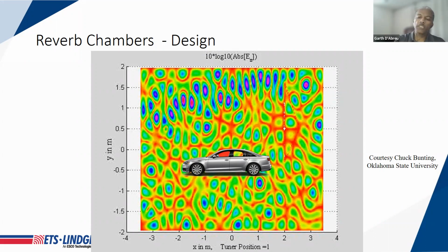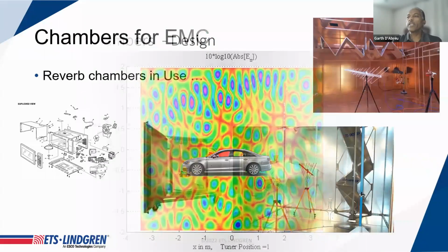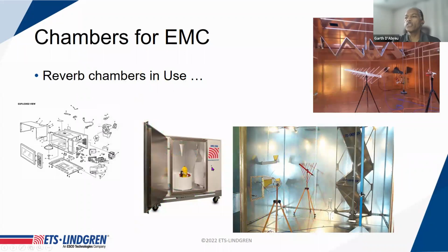One of the things I would say, and I think this provides a little bit of confidence in the technique itself, is that when compared to the method that's used in the communications industry for testing handsets, small wireless devices, base stations, they are able to achieve levels of uncertainty that are of the order of fractions of a dB to a dB in terms of field uniformity or field homogeneity within that reverberant environment.